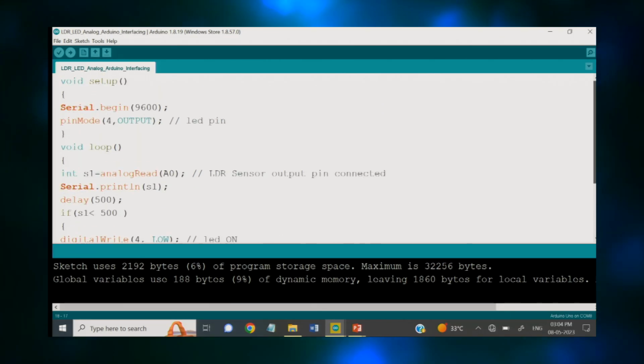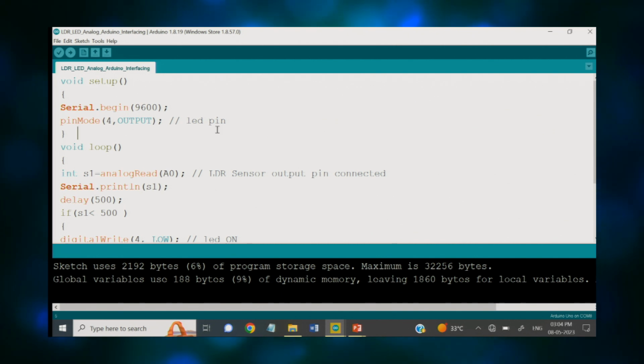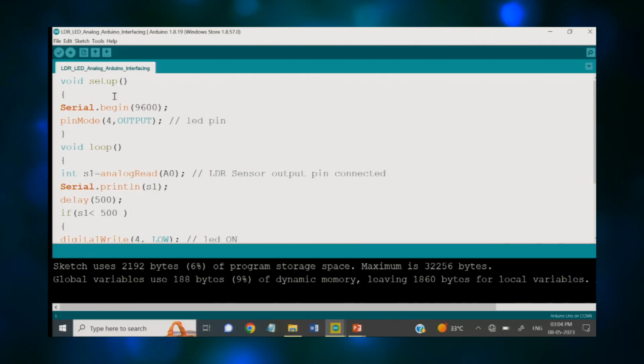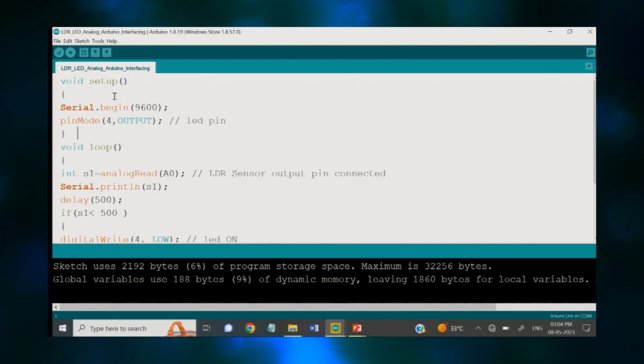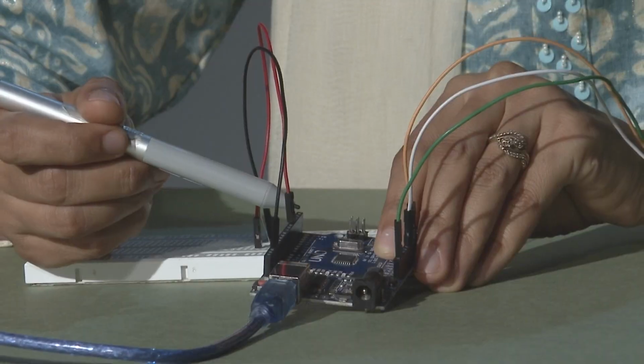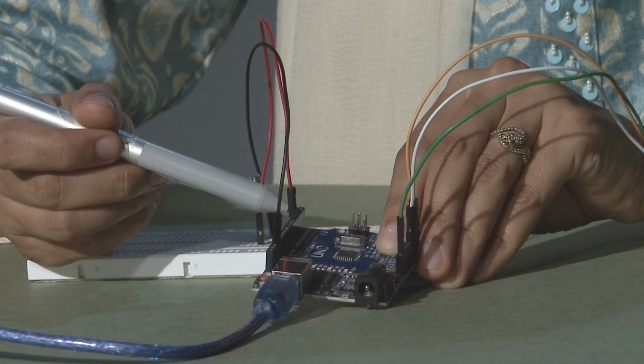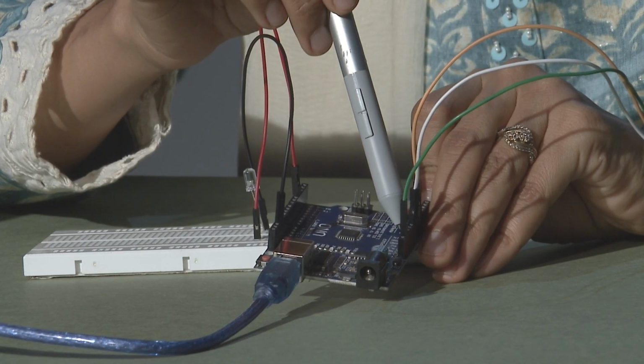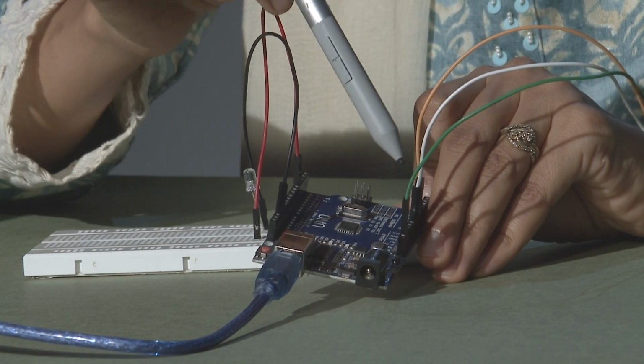So, this is the entire sequence of code we have created over here, and next to this we are now ready to interface it to our hardware terminal. First of all we need to verify that your connection is right. So, let me check if we have connected the LED on pin number 4, that will be first we have pin number 0, 1, 2, 3 and 4. So, this is right, and similarly on A0, that is the first-most pin on the analog port where I have connected my LDR. So, the same sequence we have in the software.